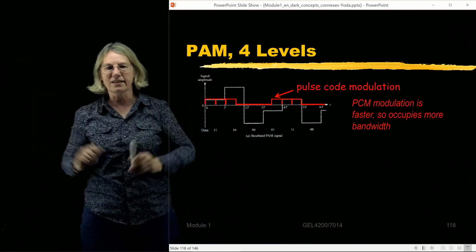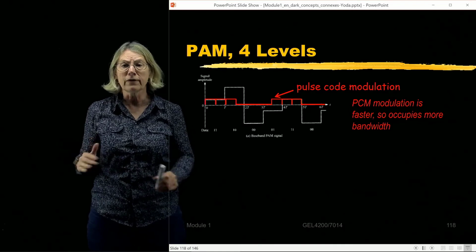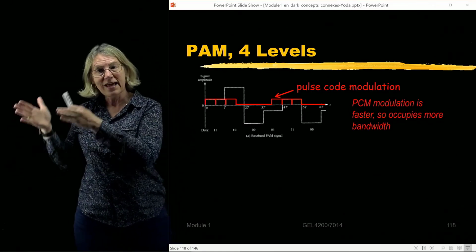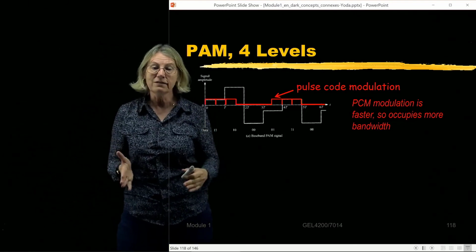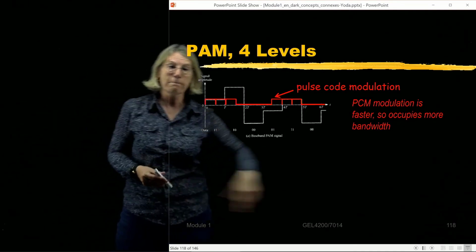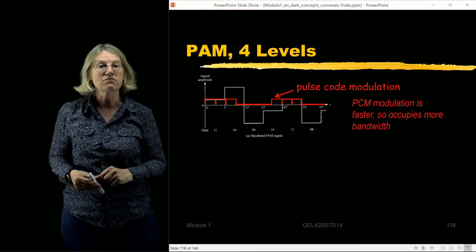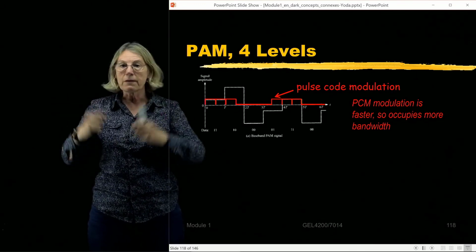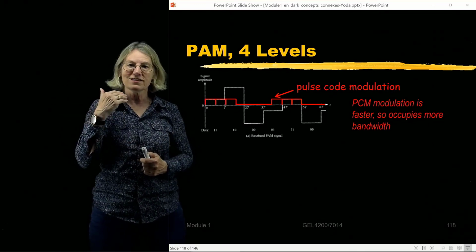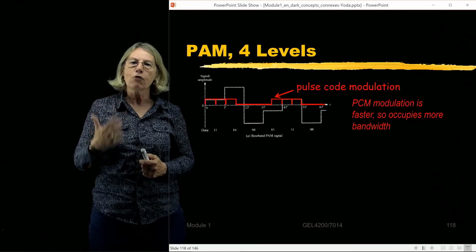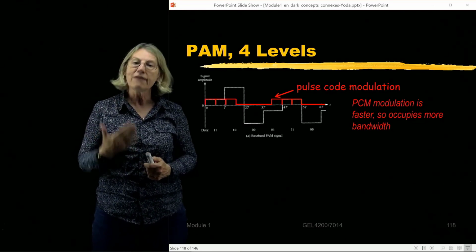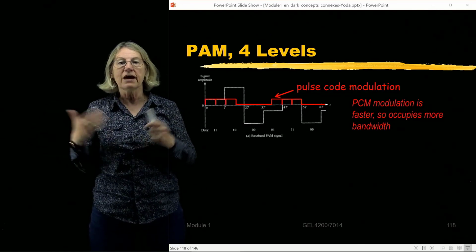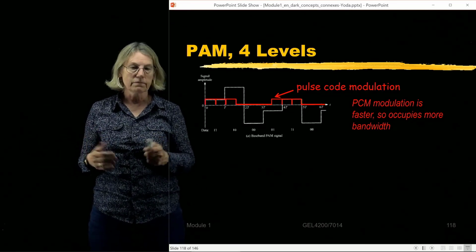We haven't really studied anything about digital communications, but already we know that if we have these two choices, do I use a binary, two-element alphabet, or do I use a larger alphabet? Well, the impact is going to be on the bandwidth occupied. And bandwidth occupation is a very, very important feature of communication systems. So my point now is to just give you this feeling for how choices on waveform can have an impact on the performance or the characteristics of the digital communication system.